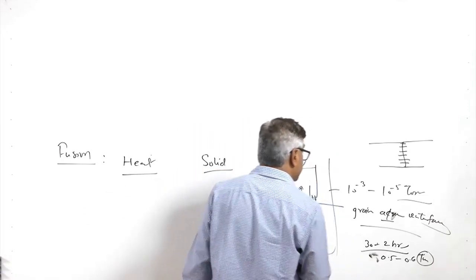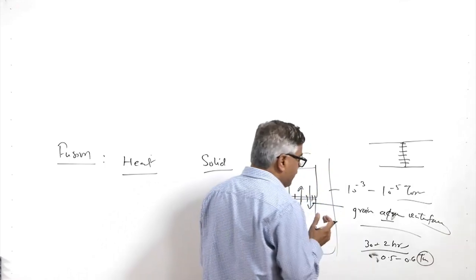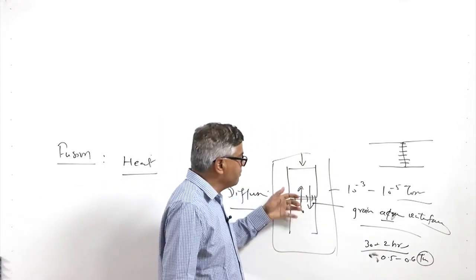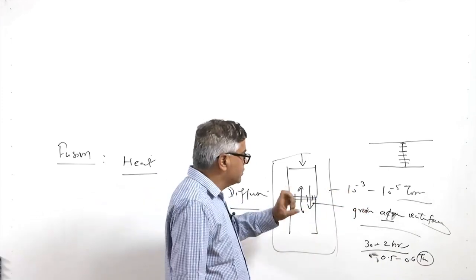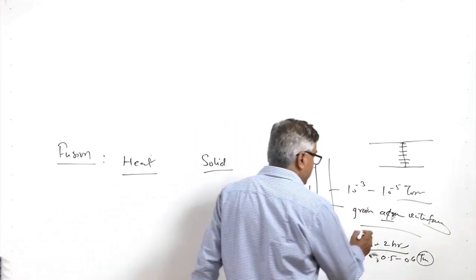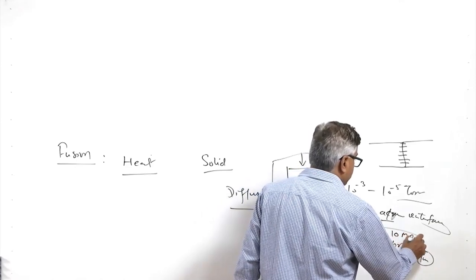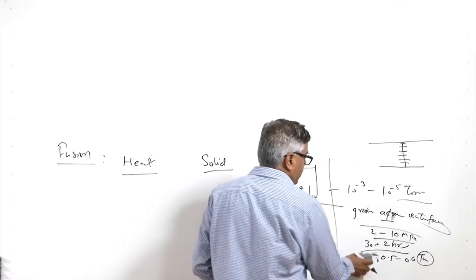Another important thing here is pressure. Pressure normally plays a big role. Pressure should not be too high, otherwise the macro level deformation at high temperature can occur. So the pressure is normally like say 2 to 10 MPa in order to have the diffusion bonds.